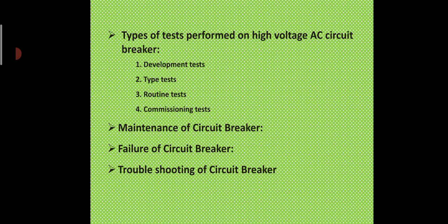Maintenance of air blast circuit breaker. It also includes operational checks, general inspections, cleaning, conditioning of air, insulations, load control kiosk, pressure gauge, pressure switches, main connections, secondary wiring and fuses, linkage of the interrupter, main mechanisms, auxiliary switches, indicating device and interlock, sequence isolator, local air receiver and pressure vessel, interrupter, isolating switches, earth connections, etc. These are the points of maintenance of air blast circuit breaker.